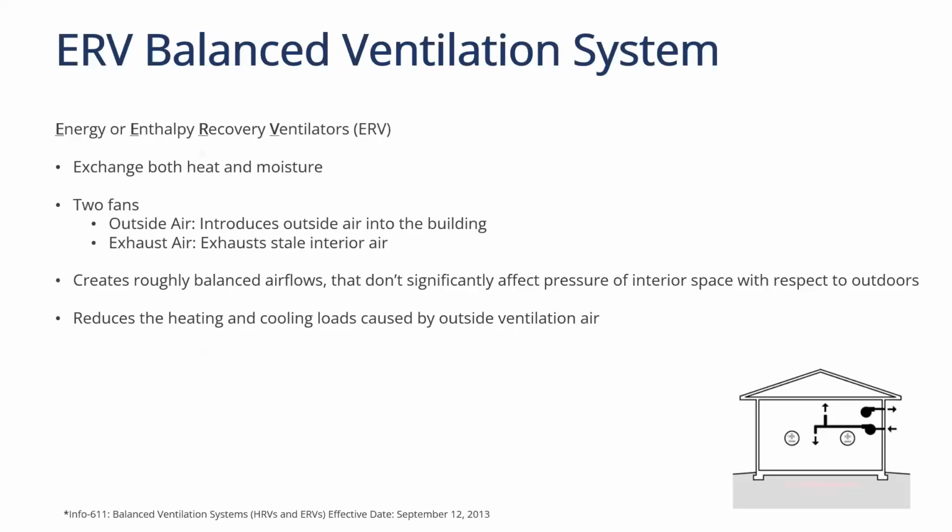So again, the ERV is one of the balanced ventilation options. That is the option that we chose to integrate with our system. It's either energy or enthalpy recovery ventilators, which is the acronym for ERV. It exchanges both heat and moisture. And again, it has the 2 fans, so you're bringing in that ventilation or outside air into the building, and then you're also exhausting that stale air either from the bathroom or from the apartment as a whole.